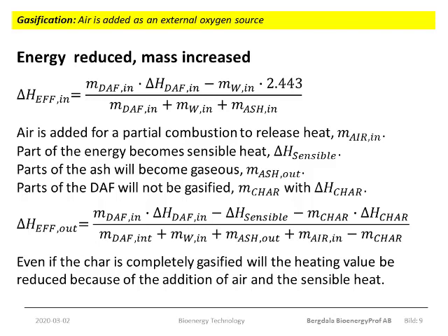So the heating value will be the incoming energy with the combustible solids, reduced by the sensible heat in the hot gas and by any energy left in the solid residual char. So the heating value is, by definition, lower in the outgoing gas than in the solid biomass.